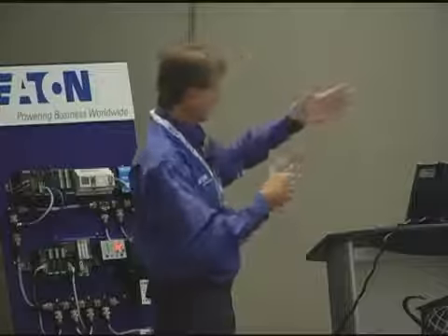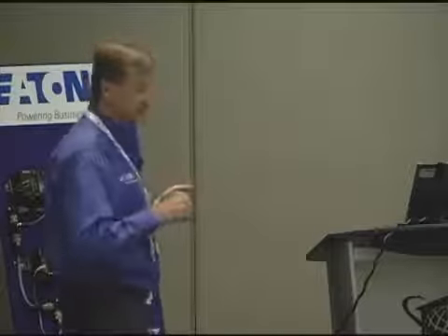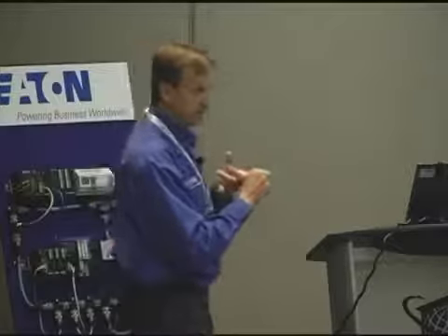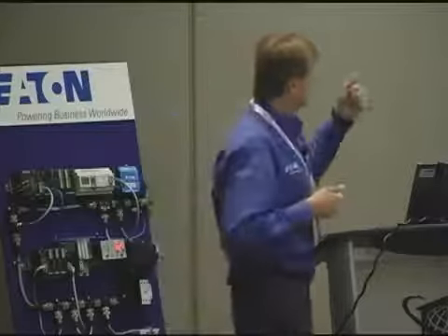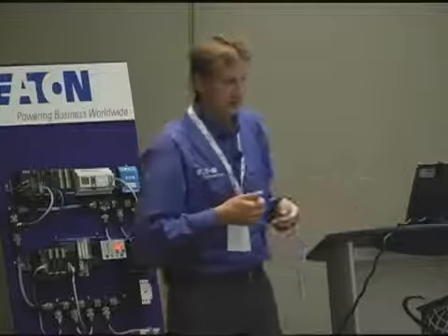Now, when we talked about Ethernet, we said we could have multiple protocols on one Ethernet network. You have to be aware that in an EtherNet/IP system over here, even though it's Ethernet, you can still only have one master with EtherNet/IP operating EtherNet/IP slaves only. You can't talk to Modbus slaves, so you still have to talk the same language. All this stuff is outlined in the implementation guides of every protocol.